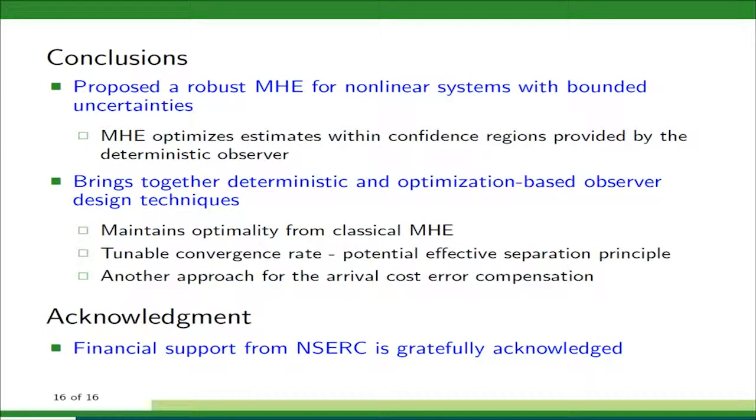Did you assume any plant model mismatch in your simulation? In the model, actually, we consider the process disturbance. There are some random values added to the model, and the model used in the design of the observers doesn't know the disturbance, but in the moving horizon estimation, it knows the distribution and the bounds of the uncertainties.